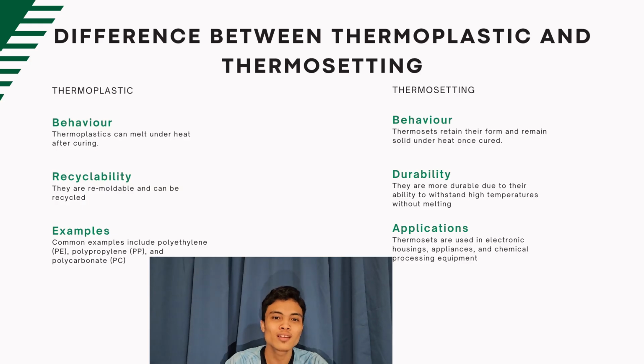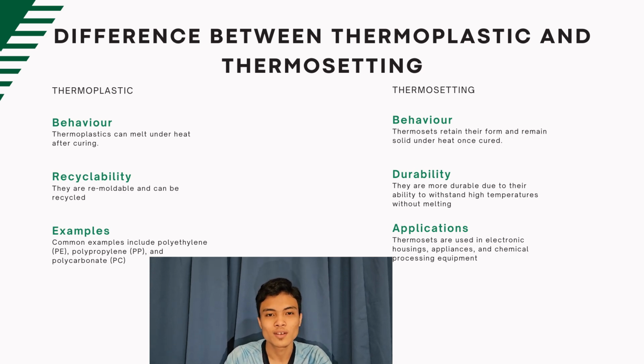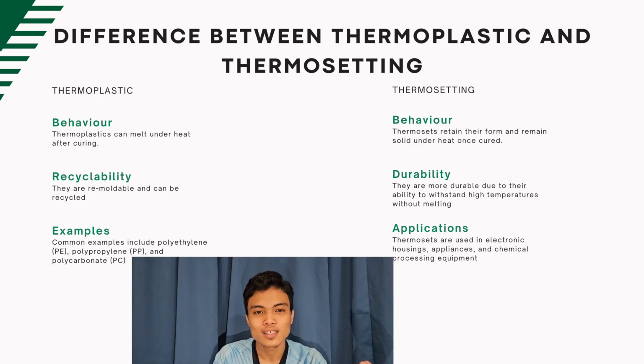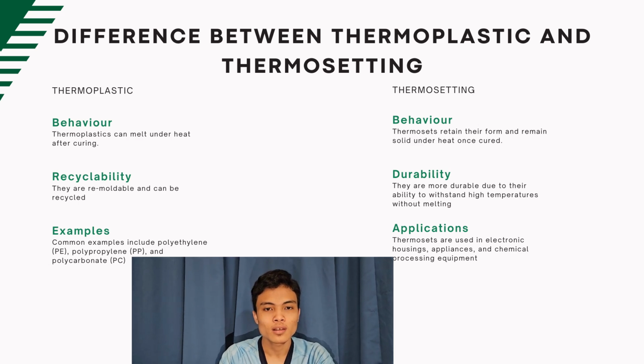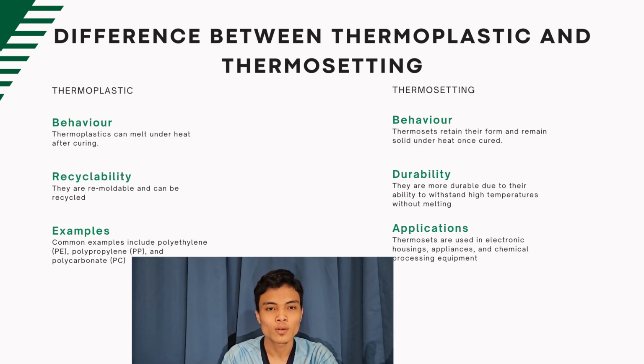So between thermoplastic and thermosetting, thermoplastic can melt under heat after curing, compared to thermosetting, which remains solid under heat after curing. Thermoplastic can be recycled because it is remoldable, compared to thermosetting. For thermosetting, durability is very high compared to thermoplastic.